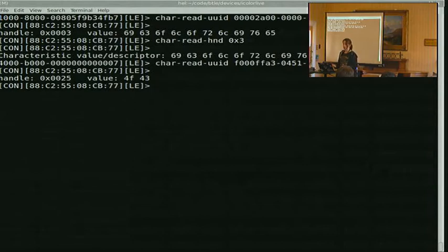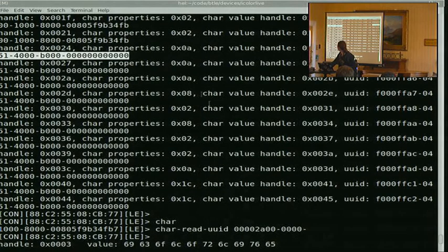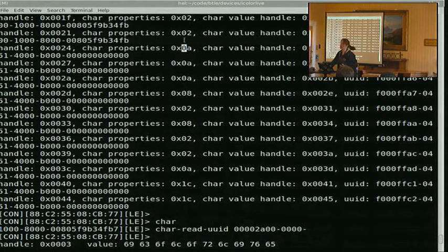It could be anything. In the list of attributes that we saw, the properties are 0x0A, which means it's read-write. We could try writing something to it, but we don't really know what that might do. We don't know what input sanitization we have. We might create a brick. We might just have a really frustrating experience of trying stuff and getting nowhere.